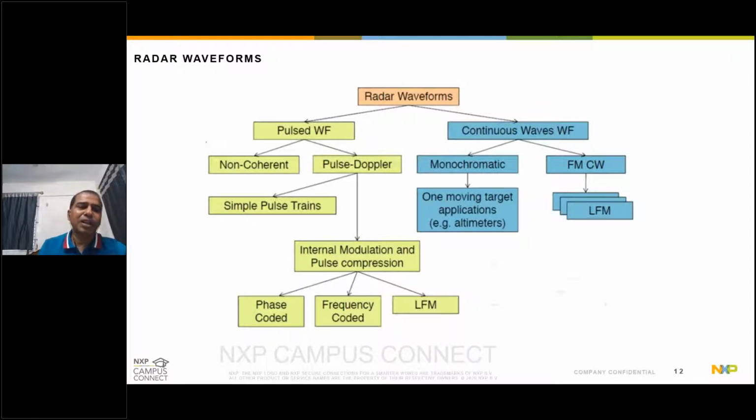A frequency modulated continuous wave radar system with its continuous measuring signals is capable of good range resolution, often as fine as 0.5 meters. So we are able to get a very good resolution. A pulsed radar system, on the other hand, is not quite as good on range resolution. It typically suffers a large blind spot in front of the radar of 50 meters or more. The resolution is not good in pulsed radars.